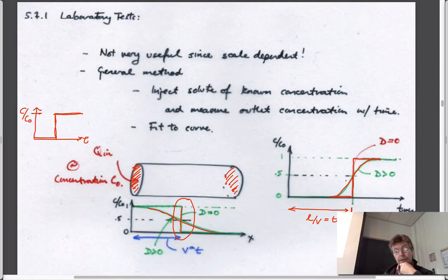And what we talked about last time was this T sub R was equal to 1. That's basically one pore volume. In other words, the fluid that you put in the upstream end has traveled downstream at one pore volume. It immediately, or is incipiently about to, break through on the downstream side and exit. And so we'd expect that to be the case. If there is spreading, then that means that sometime before one pore volume, we actually see concentrations that were larger than 0, which they wouldn't be otherwise. And so that's really inferred here.